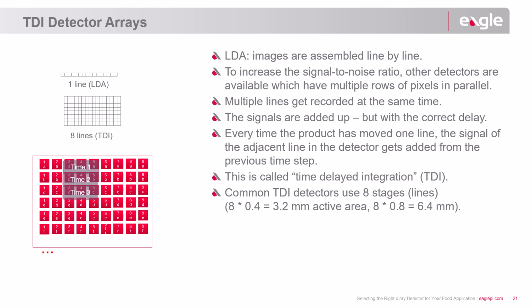A line scan detector using TDI technology is an indirect detection system that comprises a scintillator and a photodiode arranged in a linear array. In this design, the detector features multiple photodiodes in a row, sometimes just two, but often many more. Increasing the number of diodes enhances the resolution by capturing additional data points across the scanned image. This allows the system to produce high-quality images by effectively gathering optical signals as the object moves across the detector.